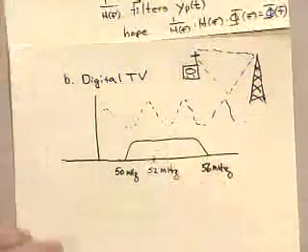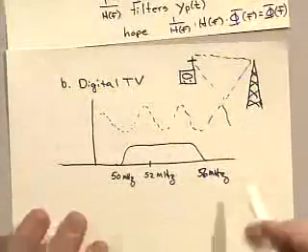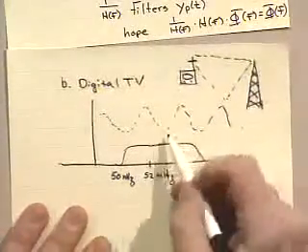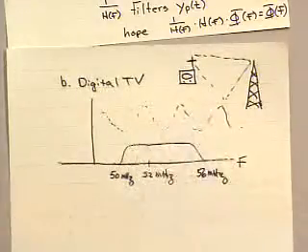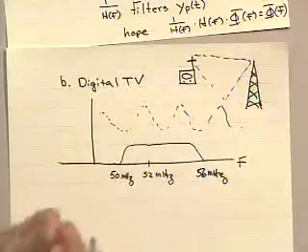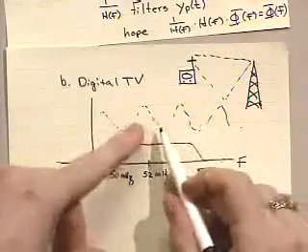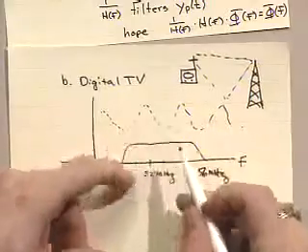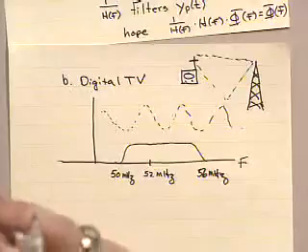And this frequency of repeat as you roll through the various frequencies, F, whether you're at 180 degrees or at 0 degrees, in which case the signals will reinforce, depends on the frequency. And the greater the delay, the more compressed this rippling will occur in the channel. So this causes intersymbol interference also. So that's a terrestrial transmission.